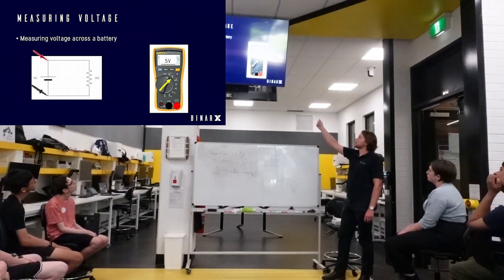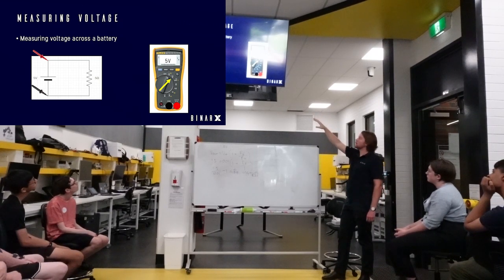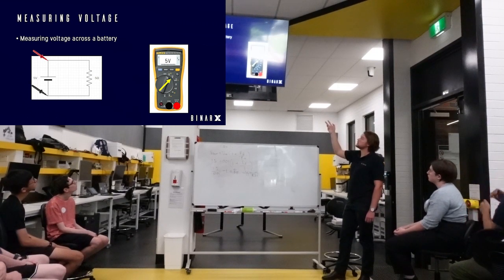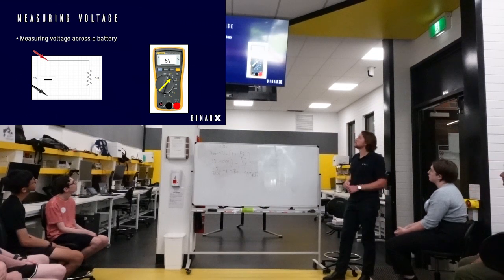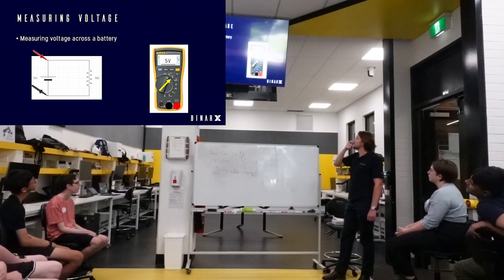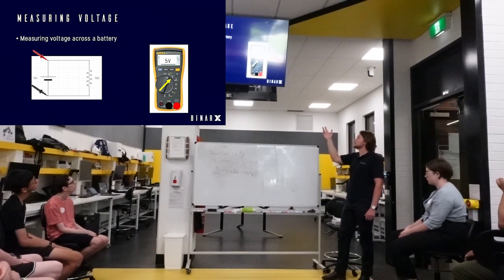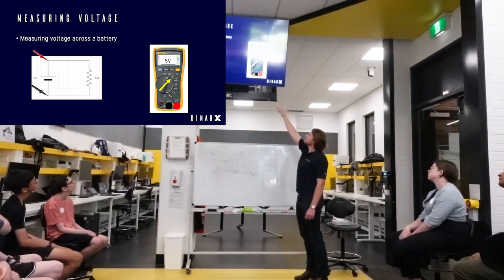So, some examples with that simple circuit from before. If we have our multimeter here, the dial's turned to our voltage setting, so we're trying to read DC voltage. If you can see the dial, there are other settings, obviously off. The voltage with the squiggly line is AC voltage, then DC voltage. The next one is the millivolts range, for measuring something really small. Resistance, with the sound bars, is what we use to check for a short circuit. You've got capacitance there, and then current AC and current DC as well. But for now, we're looking at DC voltage.